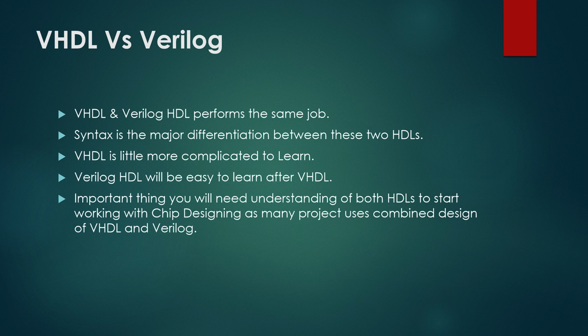VHDL versus Verilog HDL. Well, the fact is that both languages have more similarities than differences. First, both VHDL and Verilog HDL do almost the same job of describing the hardware and creating digital system design with semantics and logical design. The main difference is syntax related. Some say VHDL is a little more difficult to learn compared to Verilog HDL and requires a little more text to write, which is a little bit true, but that sometimes helps you figure out the errors more conveniently at the compilation stage.